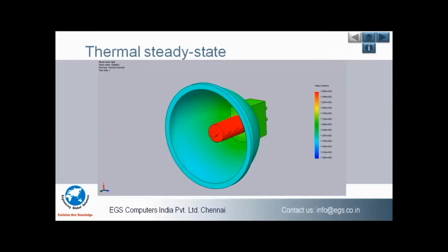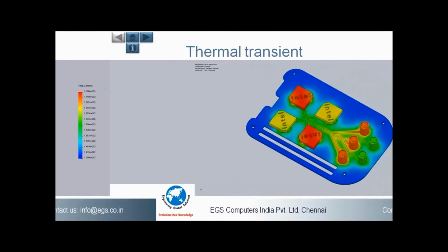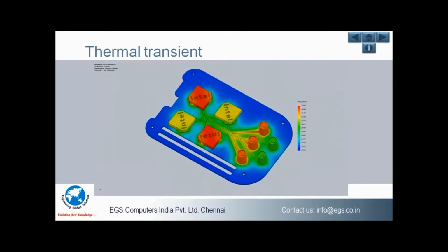For those of you who are from the automotive systems, we must consider the heat-related defects on the products also. This we can overcome using the thermal analysis, and SolidWorks Simulation can do a coupled analysis for finding the thermal stress by directly linking the static and the thermal studies. The thermal analysis can also be accessed using a steady state condition or a transient condition.